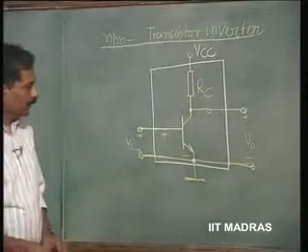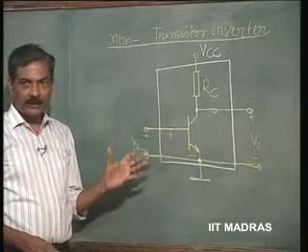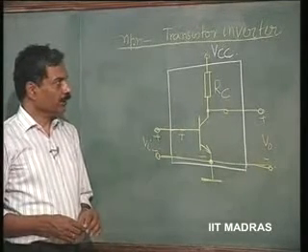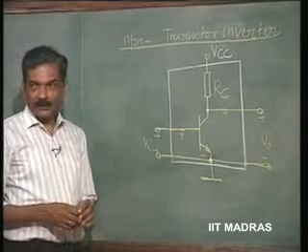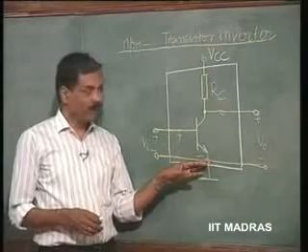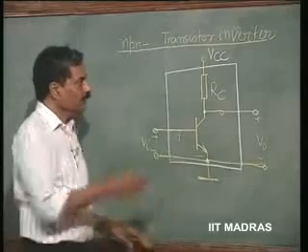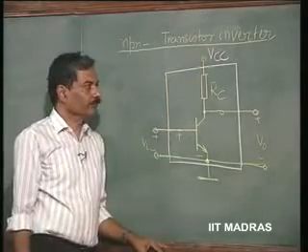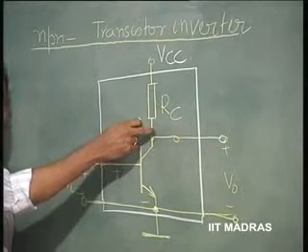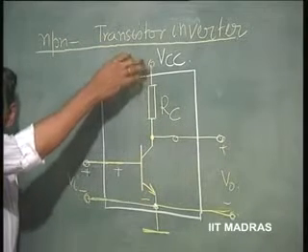We had now discussed the 3-terminal device NPN transistor as a common emitter amplifier. Let us now consider how in practice this is biased. So with respect to emitter as common, let us consider the supply voltage is VCC positive. So, this is a positive supply voltage VCC. Then automatically this collector is going to be at a higher potential than the emitter, and it can be made as high as you please by selecting VCC.